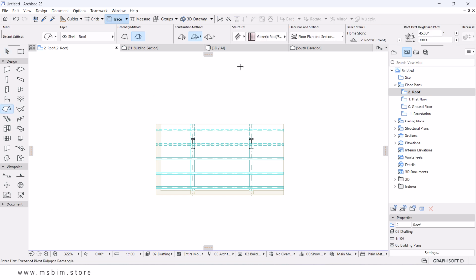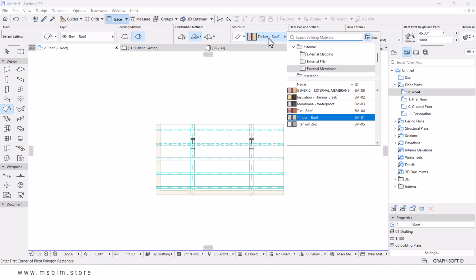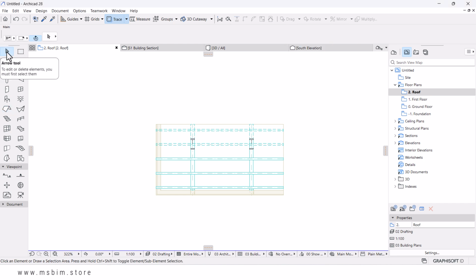From here, for the structure, we're going to set it to just basic for now, and if you select the material, you are going to have to create your own custom material, because we don't have the corrugated iron sheet, which, for example, in this tutorial I want to use. We don't have such kind of building materials in ArchiCAD in your default template. So before I place it, I'm going to create the material first.